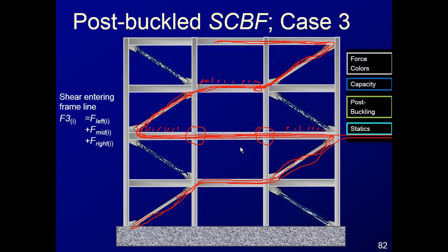And then for case 2, you're doing a static adjustment anyway. You're getting your F sub P force outside of your analysis, and then using the brace forces below. So I don't think the rigid diaphragm interferes with this at all.